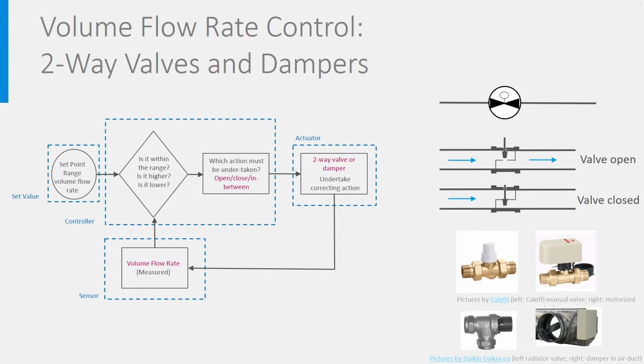In a P&ID, this is indicated like that. Look above right. The actual value of the flow, VV, is measured by a flow sensor sending its signal to the controller, which compares it to the set value Vs, after which action is undertaken on the valve. That is the meaning of the red dotted lines. It sends a signal. So, somewhere after the valve there is a sensor placed on the duct.